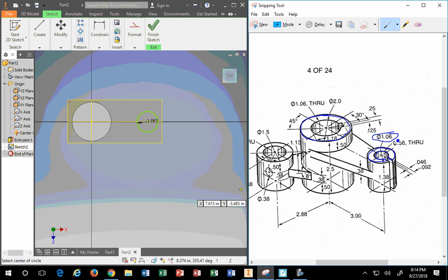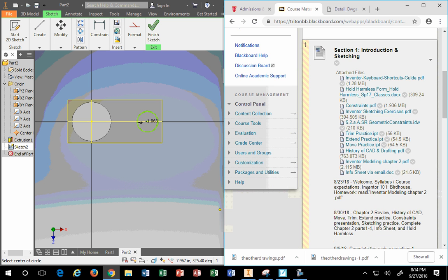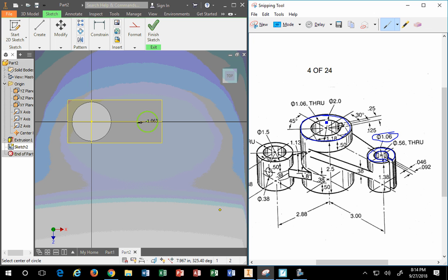Whenever we see 0.06, something of that nature, remember to go into your, I think it's somewhere in here, the chart, the decimal equivalency chart, to make sure you use the real decimal value and not the toleranced one, because in the grand scheme of things, whatever we build in here, we have to presume is going to be taken as a 3D model and sent to, for example, a 3D printer, or sent to a CNC. Okay, so no human's going to get a chance to look at that model and verify that the dimension is a true dimension versus a tolerance assigned dimension.